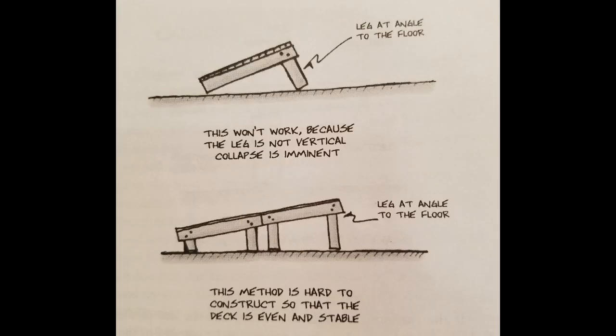Another function of a platform is that you can create the raked stage that we talked about a few classes ago. And there are, again, two methods to create this. You can create the raked stage by adding singular legs at different mitered cuts along the bottom of your platform to create that raked set. But more often than not, what that does is that it creates a little bit of unevenness, especially if your floor isn't completely level itself.